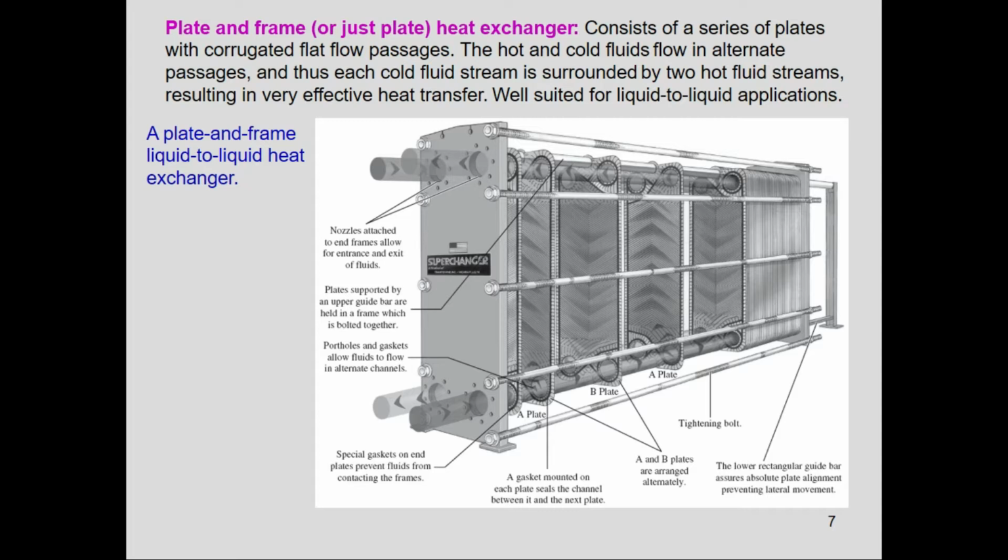The plate and frame heat exchanger can grow with increasing demand for heat transfer by simply mounting more and more plates in the configuration. So they are well suited for liquid to liquid heat exchanger applications, provided that the hot and cold fluid streams are at about the same pressure.